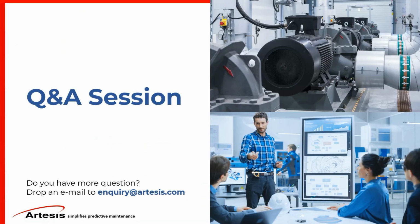Good question from Jonathan David. In order to obtain the actual flow, do you measure it or do you estimate it? We do both. If the user has some flow meter and they provide the data through Modbus to our software, then we won't have to estimate it. If not, then we will estimate it. And the error in estimating that is right now approximately somewhere between 1% to 3% error range. That's a good question.